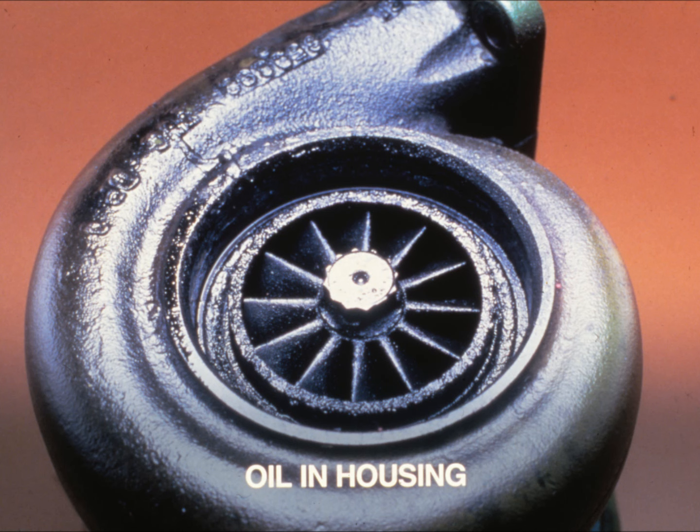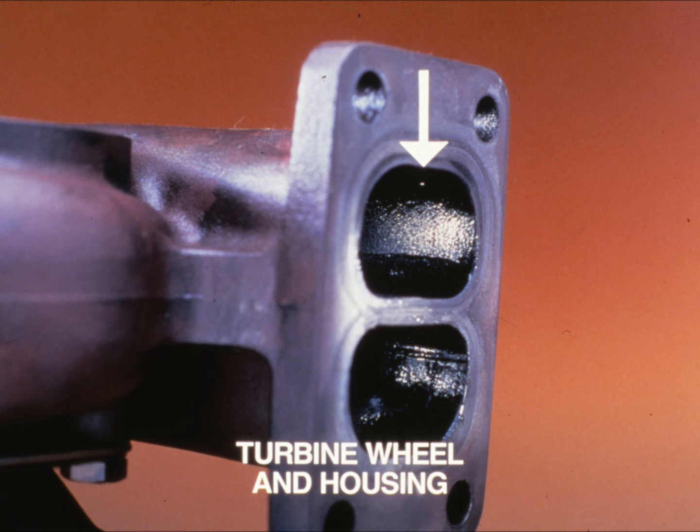Other potential causes include a restricted turbocharger oil return line or a crankcase vent. This increases the pressure within the turbocharger, which can force oil by the seals. Be sure to trace these problems and correct them, or they may cause repeat failures. An engine problem can also feed oil into the turbine housing. If the inlet to the turbine housing and the exhaust manifold are wet with oil, then a problem exists in the engine.